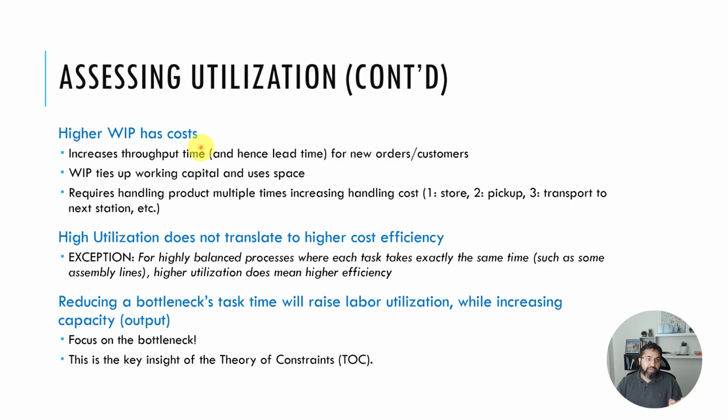And so you cannot create an extremely balanced process. When you cannot create an extremely balanced process, you have imbalanced cycle times. You're going to have blocking and starvation. You're going to have lower utilizations. And trying to max utilization is going to cost you more because of high WIP. And this is something that many people don't understand, and it just goes against their nature. They can't see people idle. They want to make everybody work all out, and they end up increasing the cost for the company. Okay, so hopefully now after this lecture, you will not make that mistake.